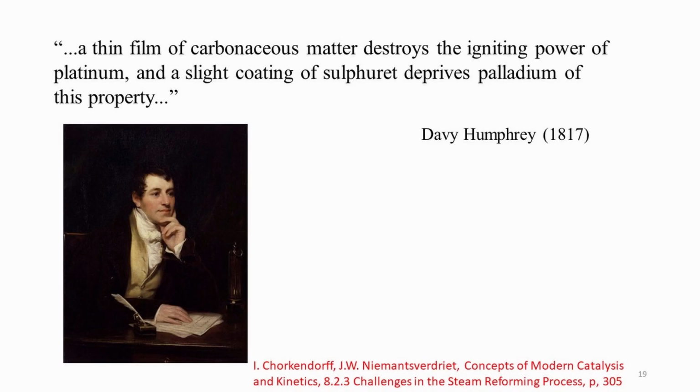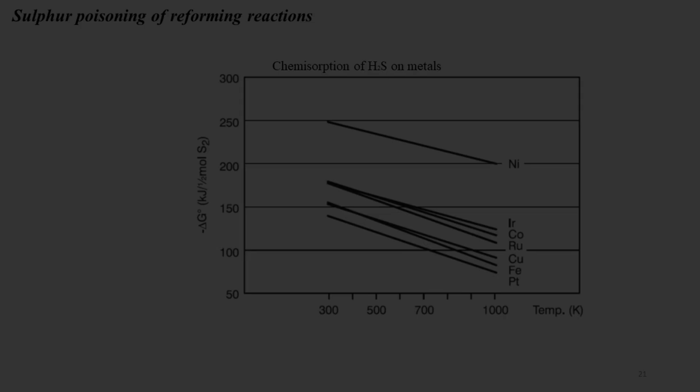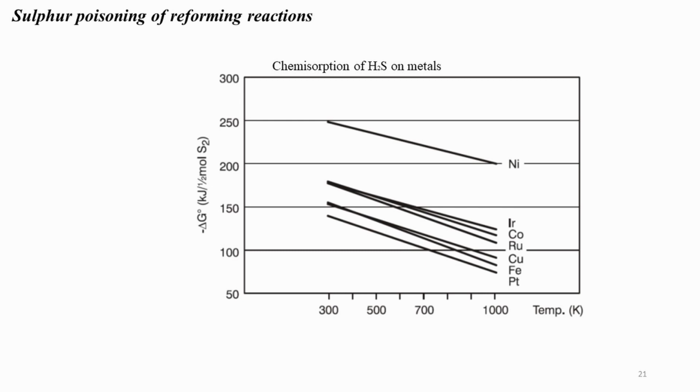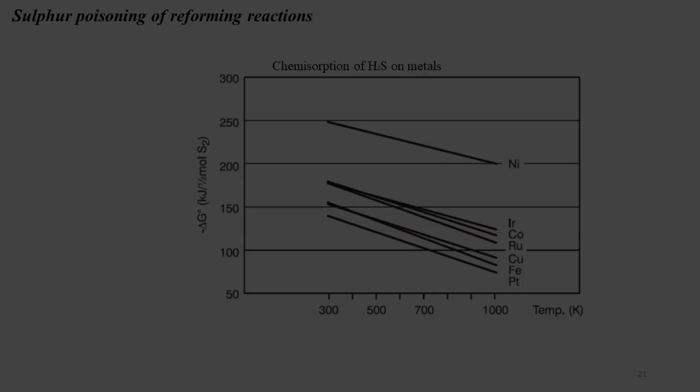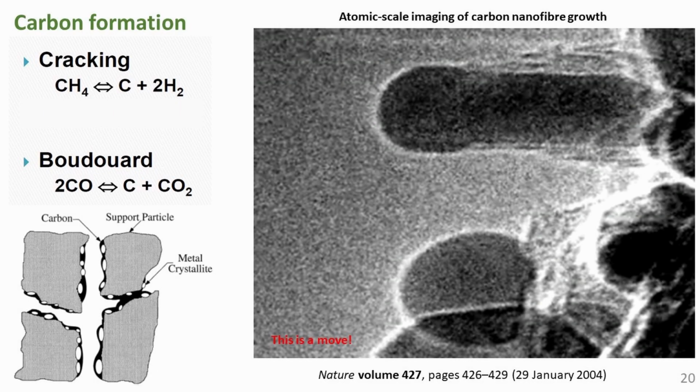Carbon formation cannot be tolerated as it may result in breakdown of the catalyst, and increase in pressure drop and flow maldistribution, which lead to overheating of the tubes locally as a hot spot or totally as hot tubes. This will limit the plant capacity or the life of the catalyst tube. Sulfur poisoning results in lower activity. The main reactions that lead to carbon formation are cracking and Boudouard.